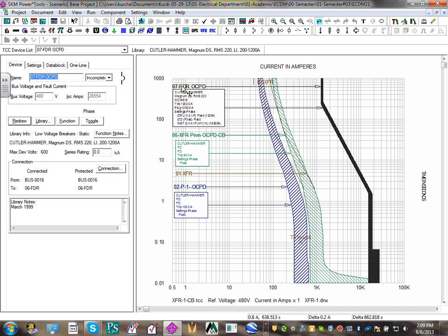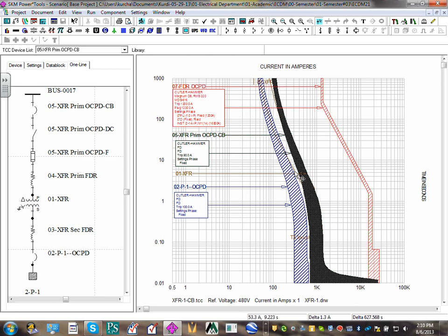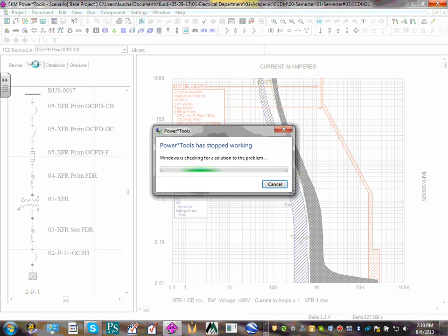So let me start from the beginning. This is the feeder that we sized. I sized my feeder much higher here. Right here is my feeder. Does it look like yours? Or did they change? Yeah, it should be. Yep. So this is the feeder for the whole system. Here's the riser. Here's my feeder. This is the one right here that feeds the transformer and multiple other transformers. I'm sorry, the feeder right above here feeds the whole feeder. Then I'm going to go to the primary. Here's my primary overcurrent protection device. I want to show you how I'm setting my primary. This is a Cutler Hammer.